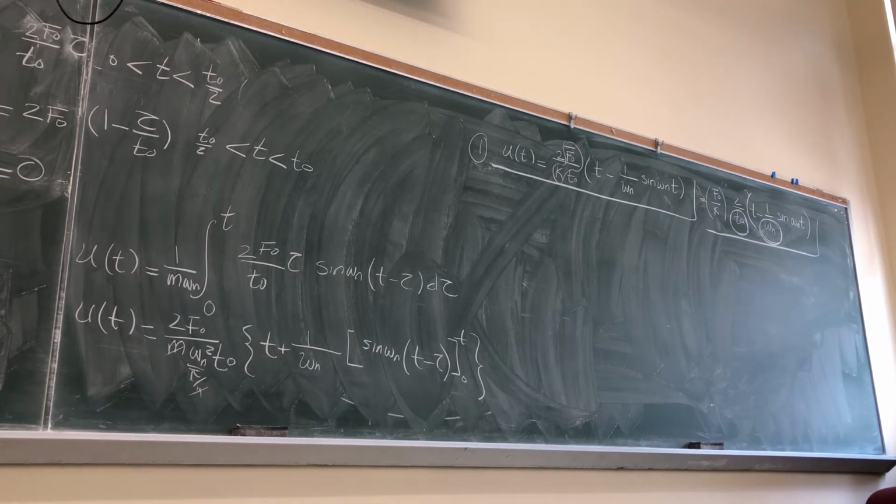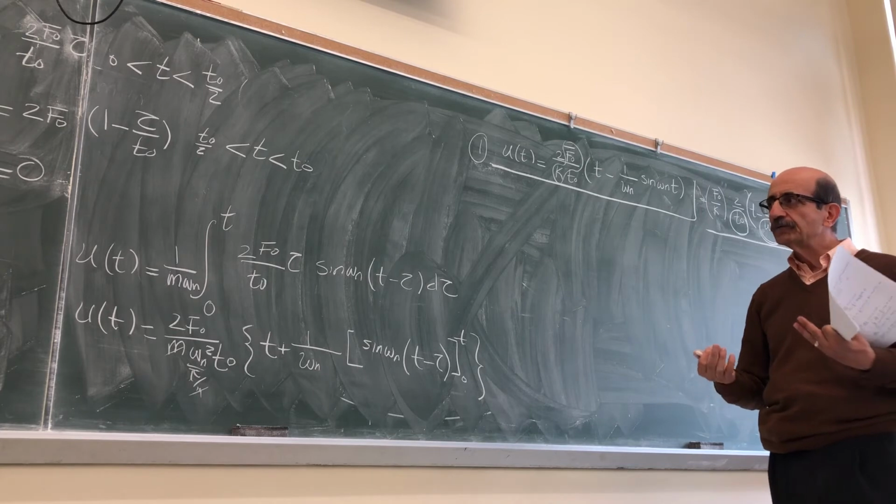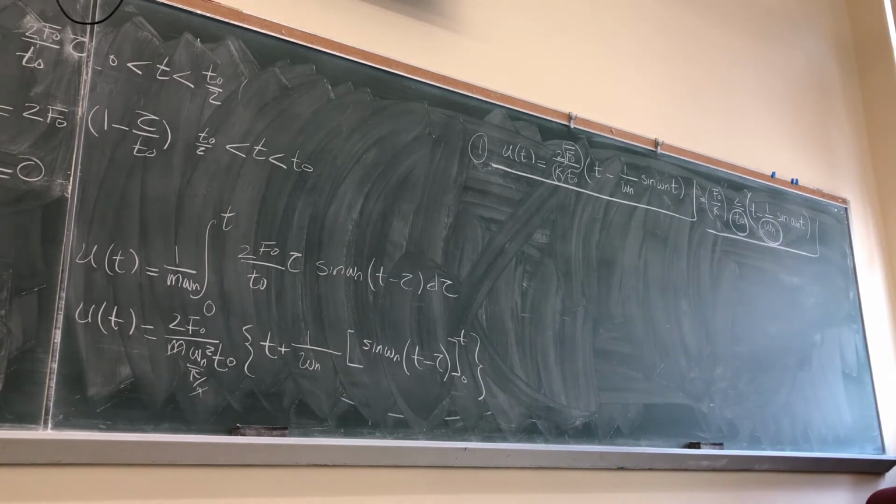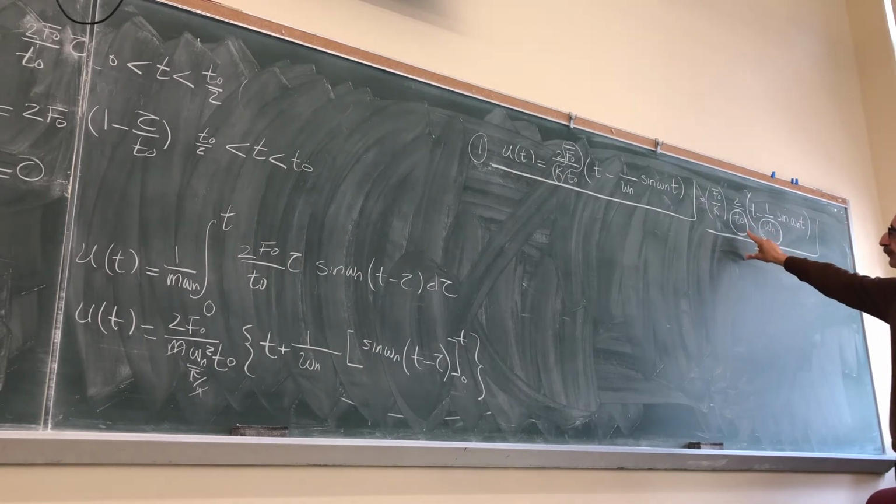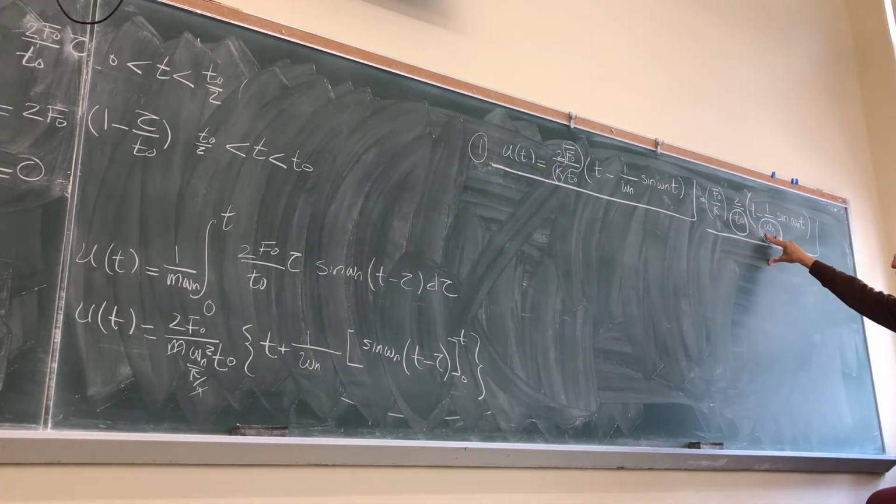So, in fact, as we will see later, we want to get a better understanding of how you develop an approach that can give you basically maximum response as a function of these two, which we'll get to, shock spectrum. But make an observation here that the response is always a function of 2 important parameters. Depends on the natural frequency of the system as well as the time duration.